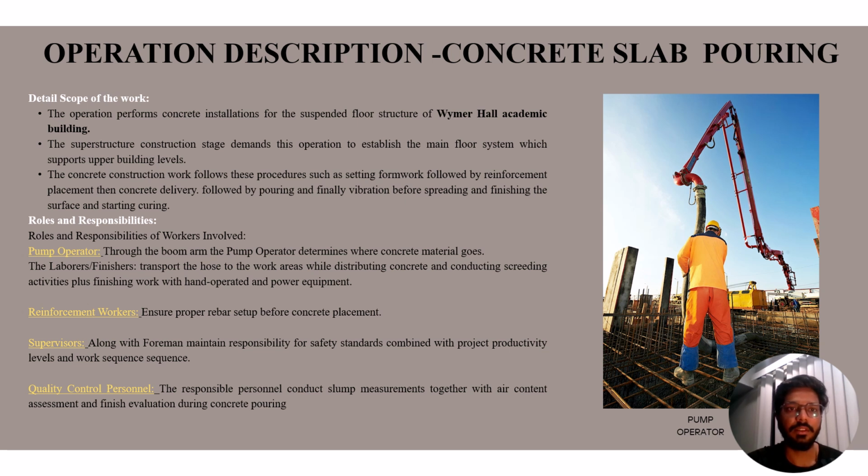Talking about the details of the scope for this work, the workers need to set the formwork in a perfect manner with perfect measurements, and along with it, after delivery of the concrete, it should be placed on time so that it doesn't settle down and the strength can be gained.